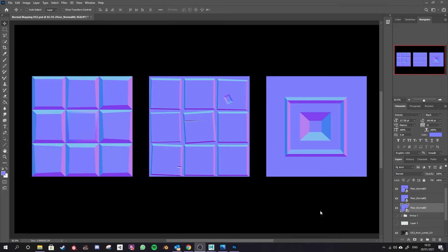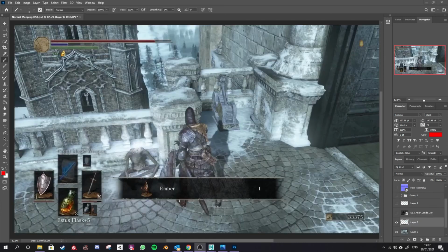This is what the normal maps turned out like from those 3 examples. So you can see here how the different angles are represented in different shades of blues, magentas, and purples. Looking back at the example that we gave of Dark Souls 3, you can see just how simple some of the geometry is. All of these shapes here are effectively just sheets. They are big sheets of geometry. All of this is not geometry data. That is all normal mapped down, either again using Substance Painter, which we'll go over later, or using the technique that we showed in Maya.